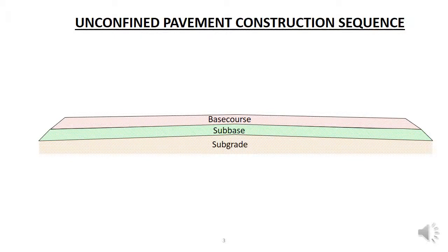An unconfined pavement does not have a Kerb and Channel confining the base course. Instead, there is a tapered edge leading down to a side drain. The issue here is how to get full compaction of the road width. Rollers cannot go close to the edge of the road as they could tip over the edge, or the edge could collapse under the weight of the compactor.